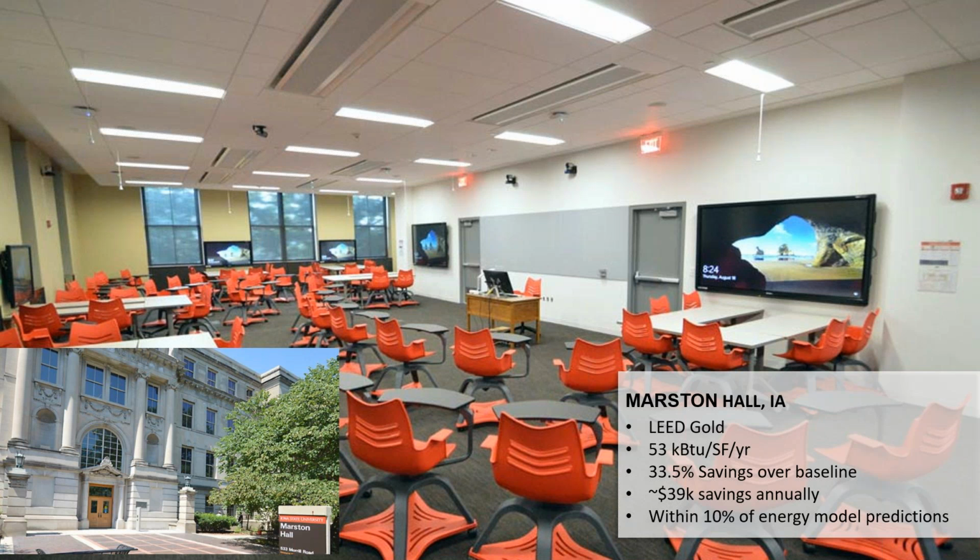So lastly, we have Marston Hall in Iowa. We wanted to mention this one. It's another LEED Gold project, and they were operating at about 53 kBTUs per square foot per year. And they achieved just over 33% savings over the baseline. Again, you're seeing a trend of roughly 30 to 35% savings over baseline, and it realized about $40,000 of savings per year, and pretty close to the initial energy model predictions.